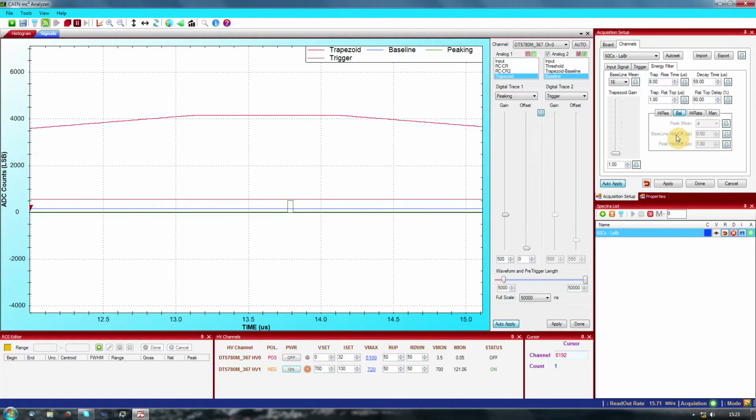Moreover, it is possible to configure other parameters: the number of samples averaged to provide the trapezoidal height, the hold-off of the baseline restoration, and the hold-off of the trapezoidal peak sampling. This last prevents trapezoidal peak sampling too close in time to a valid sample peak. The settings can be set to be suitable for a higher resolution measurement, a balanced setup, or for a higher rate condition.